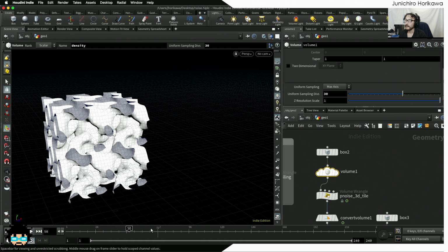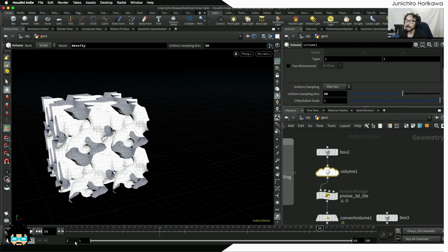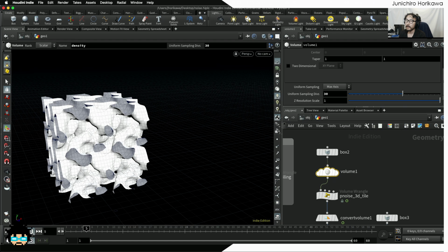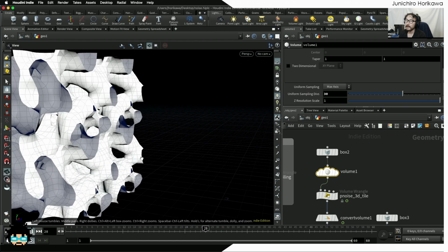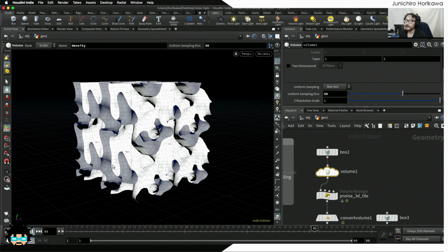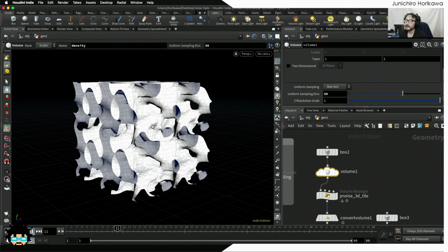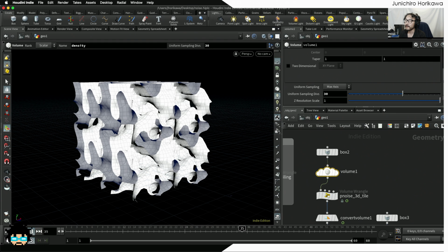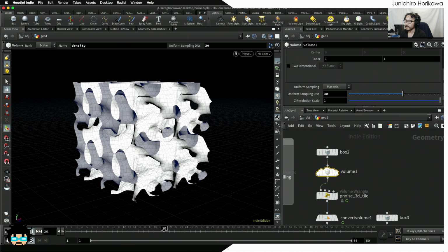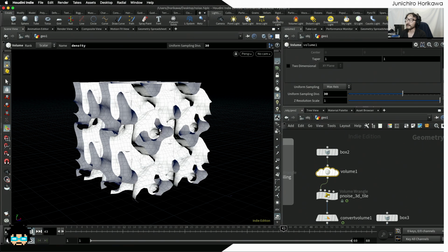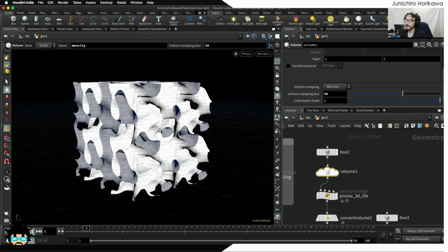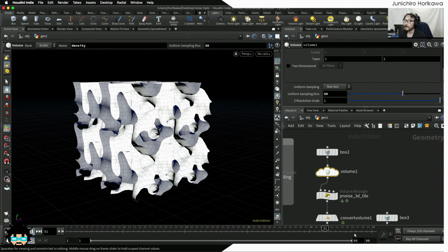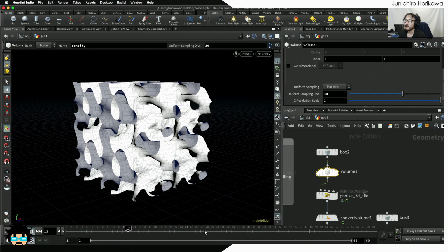And maybe the time is a bit too slow, so I'm going to set it to 60. And you can see it's changing the value from 0 to 1. It changes the shape just a small bit. Maybe the tile size, or the repetition size, for the fourth coordinate, which equals 1, is a bit too small. Maybe we could increase that as well. But you can see that it's smoothly connecting the animation from end to first.